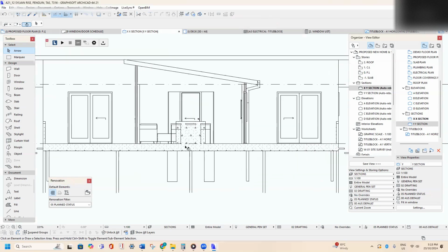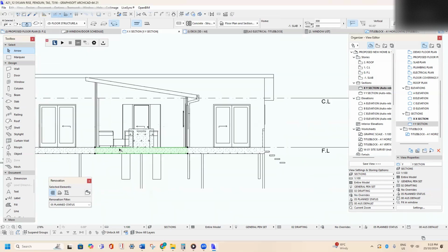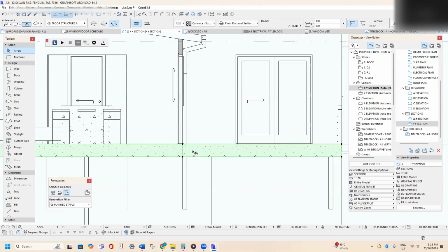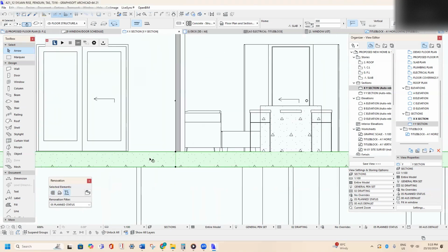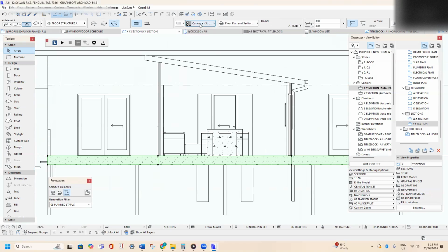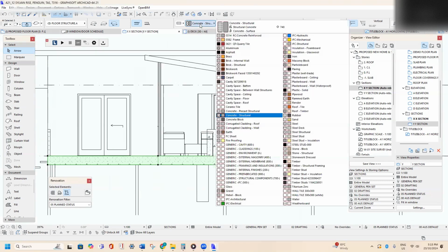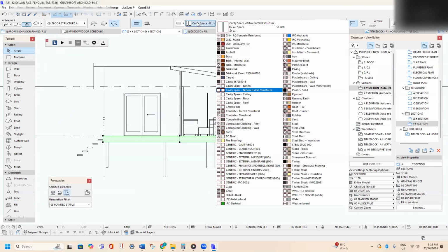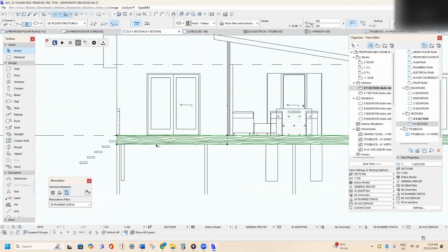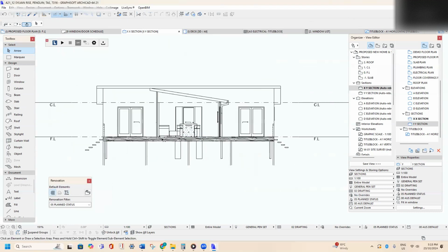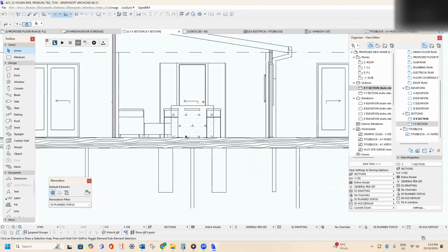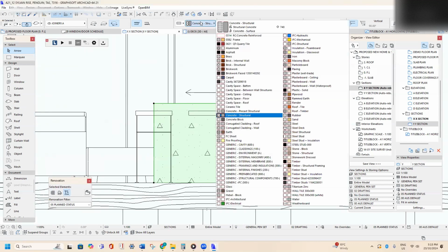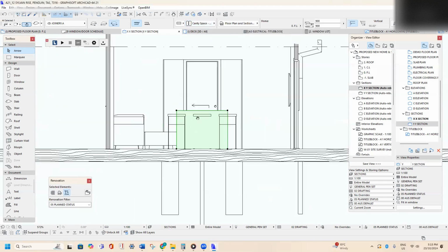Okay, from here, a couple of things to change. If you click on the floors here, it's showing up as a concrete fill. If you go up to this structure here, click on that and choose any of these, actually we'll make it a timber one. So if you find, say, roof timber, click on that one. That'll show it as timber subfloor, timber floor frame. And for the bench here, change that to cavity.